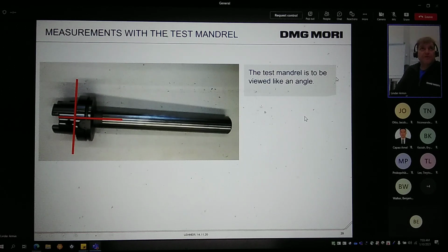So very important that we use that tool with good cleanliness, and also that the surface is clean. And also after we use the mandrel, we have to protect it from sweaty fingers, so we have to be prepared with some, how is it called, some oil or CRC.